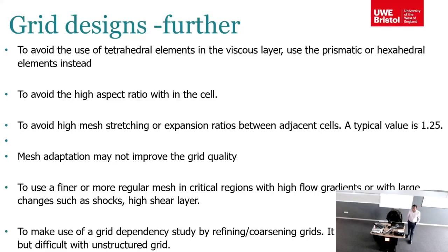You can do mesh adaptation, but mesh adaptation may not improve the grid quality. And again, use a very fine grid in the critical areas. You can do a grid dependency study, and initially make sure you know what you are doing.